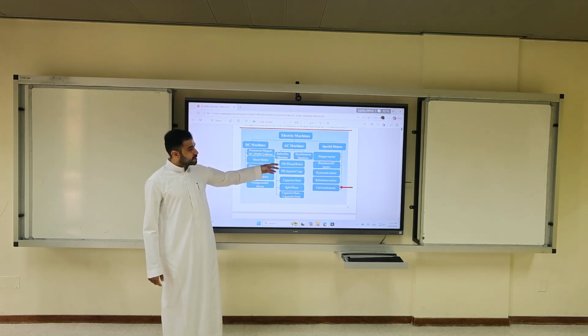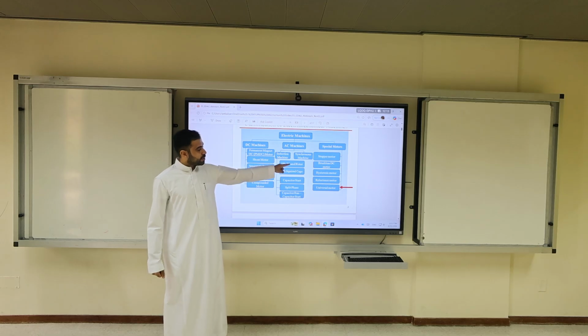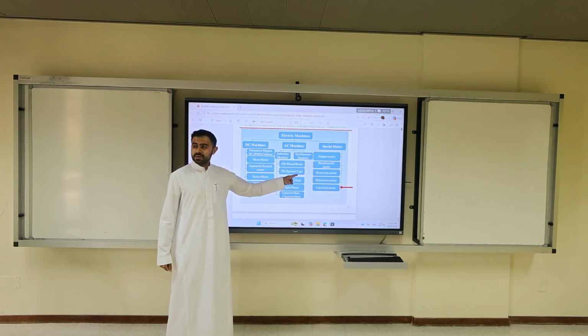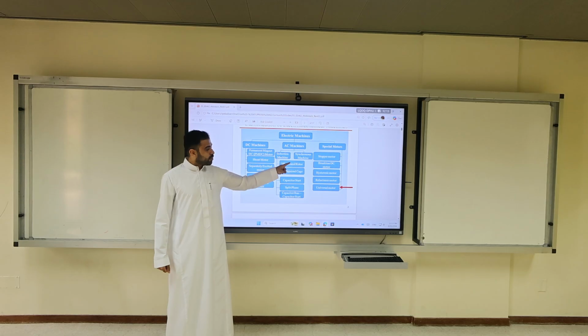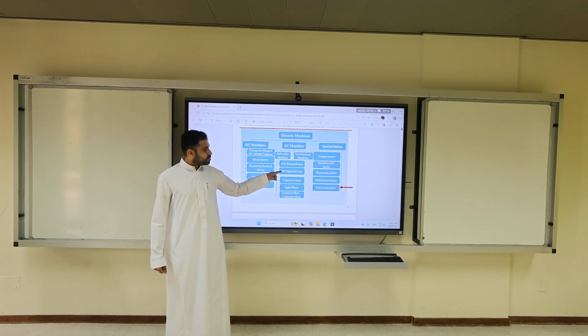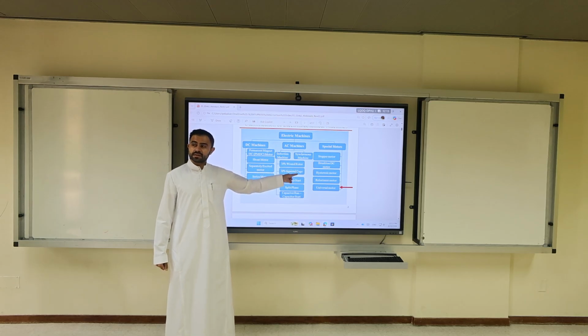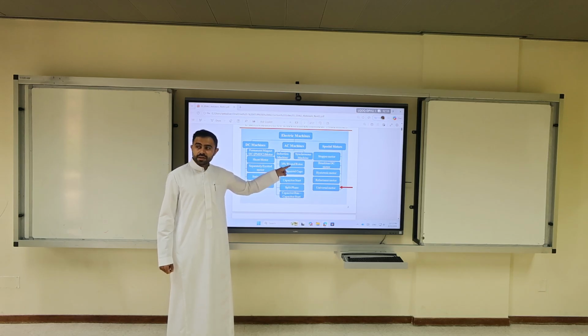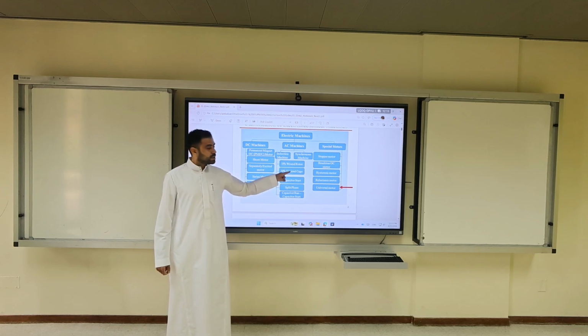So in E360 we covered what? 3-phase wound rotor and 3-phase squirrel cage. You remember them. We also now know how to control them. And a very common question in the exam: true or false? I can control squirrel cage using external resistor. False, you're right. You cannot. The external resistor is best for wound rotor because the squirrel cage is a short-circuited cage. You cannot insert resistance to it.